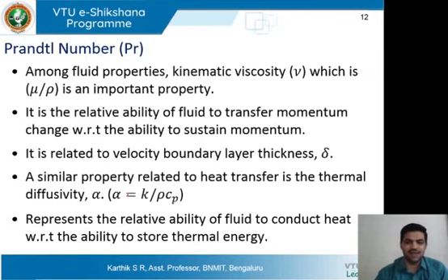So this actually indicates or represents the relative ability of the fluid to conduct heat with respect to the ability of the fluid to store thermal energy. So it is somewhat very similar to the kinematic viscosity definition. Conduction of heat with respect to thermal inertia or thermal storage. So we can put it in those terms.